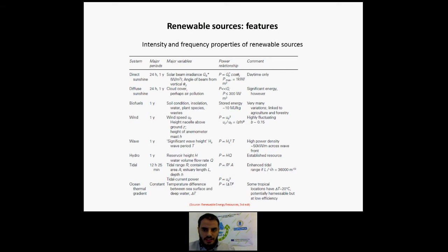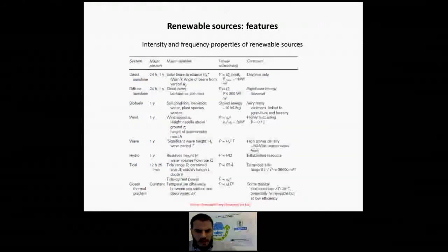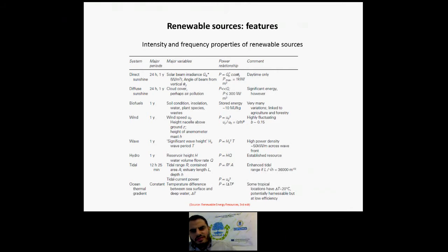Second, heat supplies, such as biomass combustion. Well, these sources provide heat at high efficiency. However, the maximum proportion of heat energy extractable as mechanical work, and hence electricity, is given by the second law of thermodynamics and the Carnot theorem, which assumes reversible, infinitely long transformations. In practice, maximum mechanical power produced in a dynamic process is about half that predicted by the Carnot criteria. For thermal boiler heat engines and internal combustion engines, the maximum possible in practical terms is a quality of about 35%.